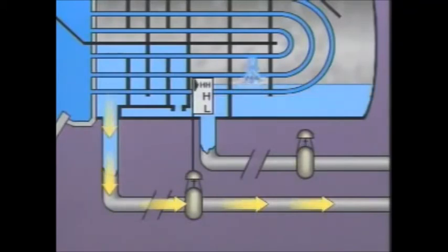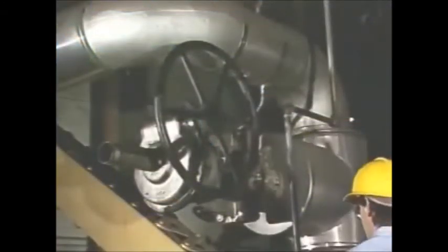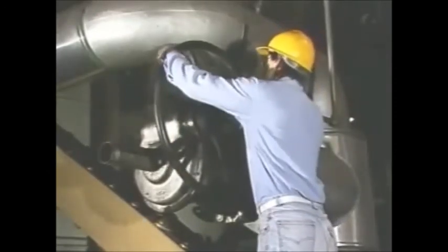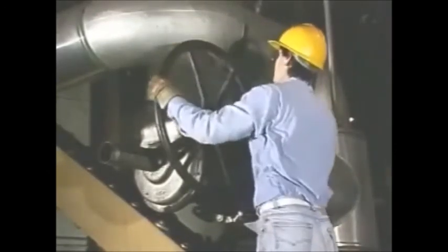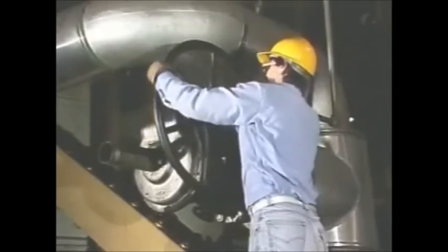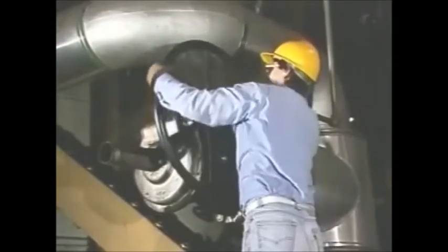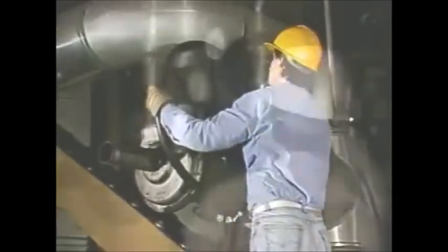As a tube leak becomes larger, the volume of water flowing into the shell side of the heater can exceed the level control valve's capacity. Then the emergency drain valve must be used to control the level in the heater. A large tube leak is a serious problem that calls for immediate attention because it can allow water to enter the turbine. To prevent damaging or destroying the turbine, you should isolate and bypass the heater as soon as possible.